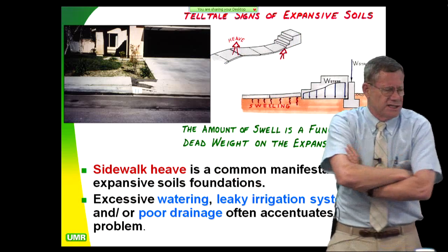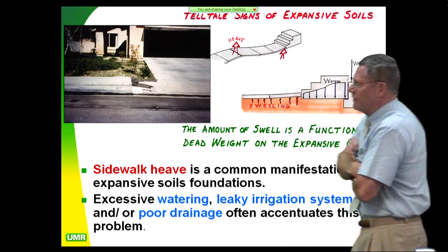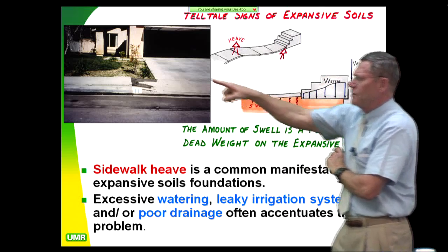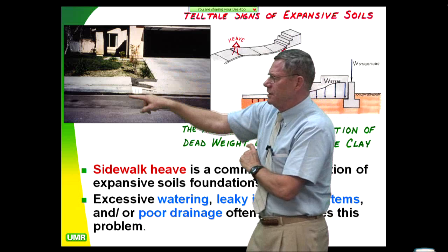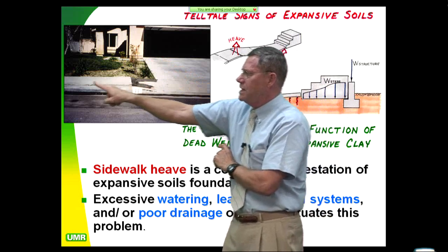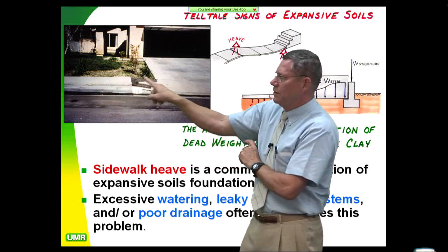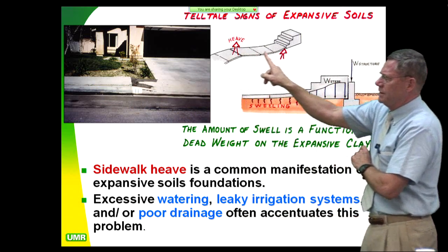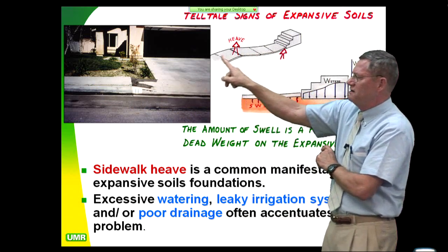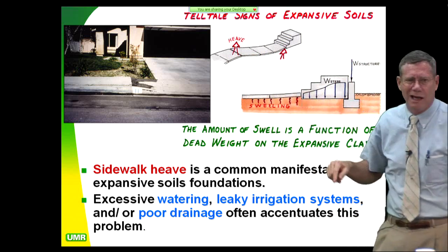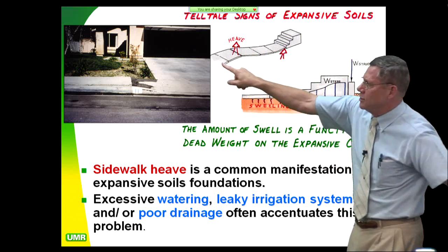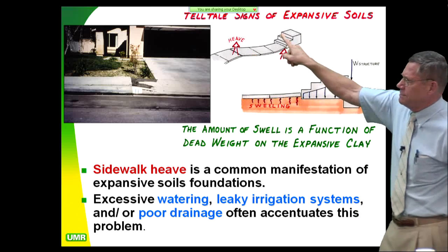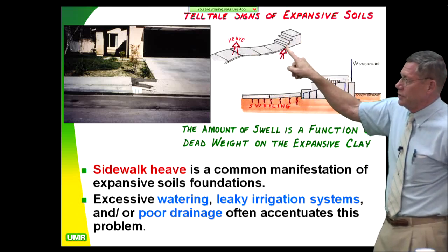What are the telltale signs of expansive soils? Well, you don't have to be a rocket scientist. You just have to have a little bit of training. And one thing is you drive by the residence and you look for stuff like this. You look for a heaving sidewalk or a heaving driveway, heaving flatwork. Flatwork doesn't weigh very much. Sidewalk going up to a house might be 3 inches thick if you're lucky on a good day. And so this is going to heave very, very easily. Whereas the steps are a lot heavier per unit bearing area.